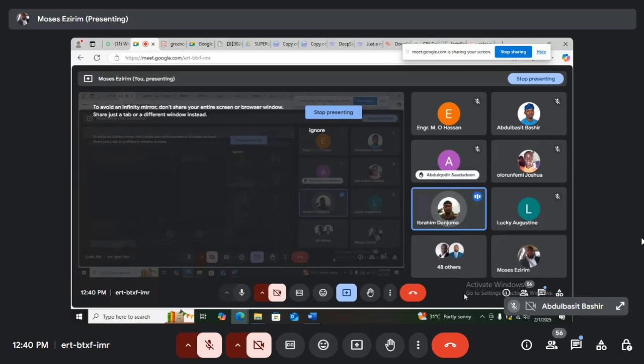All right, thank you. If you are sizing this kind of system, you need to consider what the OEM of the generator says about the generator. We are going to look at that in the course of this free training, because every OEM says that there's a minimum genset loading. You must not run the generator below a certain percent. So once you understand that, then you design your PV based on that. Don't worry, we're going to see everything in this free training.